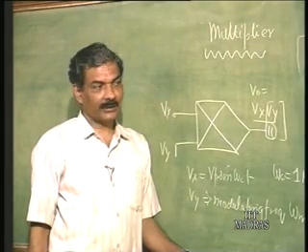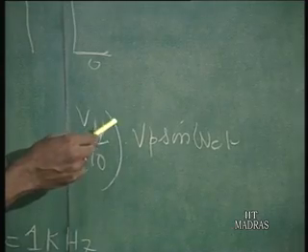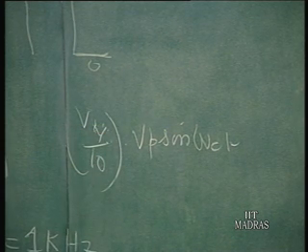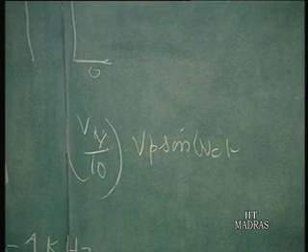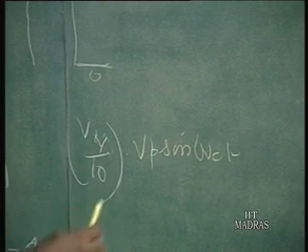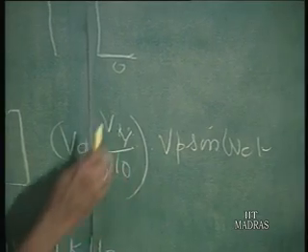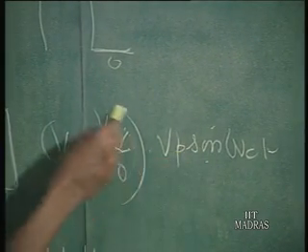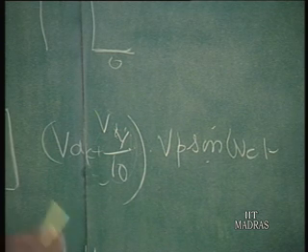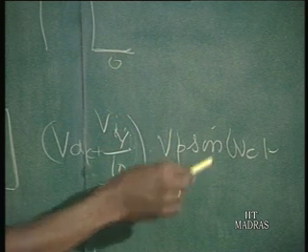In the last demonstration, you saw the gain was varying from 0 to 1, 0 at some interval and 1 at another. It is called frequency keying. Now, if you want to convert this into AM, amplitude modulation, you have to make it non-ideal. We want the gain to vary from some value to some other value. That means we have to apply a DC plus the modulating frequency. The DC will bring the carrier and the modulating frequency will change the amplitude from some value to some other value. So, we have now an arrangement where we have added the DC and the square wave at 100 hertz. So, that output is an AM.